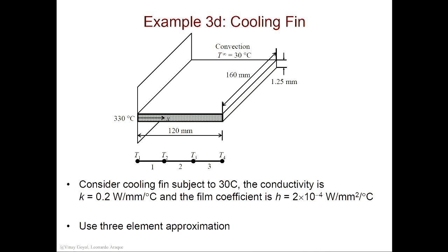Will that cool faster than just me putting on just water? Because I'm shooting at a high velocity, well, then the H is going to be higher. You're going to lose heat faster. So this is a heat transfer coefficient, and it depends on the velocity of the fluid too. Okay? In this case, I'm just giving you a lecture on something else.